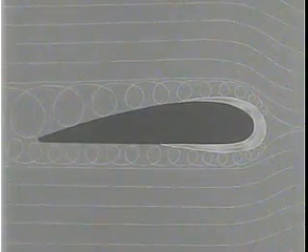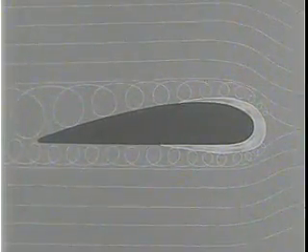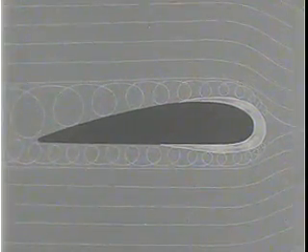When ice first appears, it has no serious effect, but gradually it builds forward and along the top and bottom surfaces. As the ice reaches the points of maximum camber, the shape of the airfoil has been drastically changed. Now the airflow is disrupted, drag is increased, and lift reduced. It is the shape rather than the weight of the ice which accounts for icing hazards. Aerodynamic capability is at a minimum. The stall speed of the aircraft is higher than normal, and a dangerous condition exists.